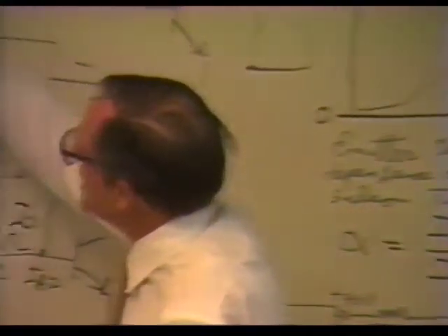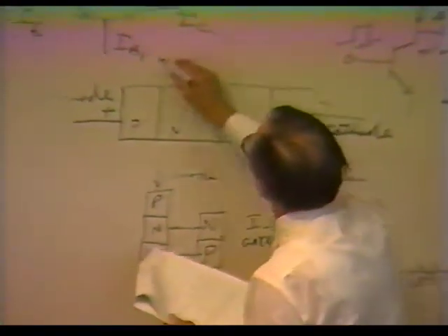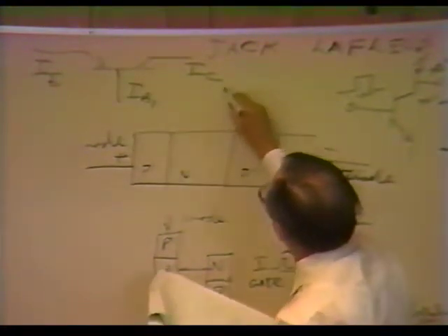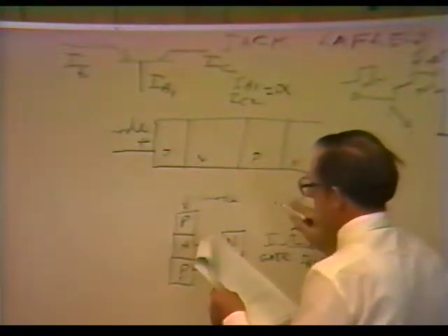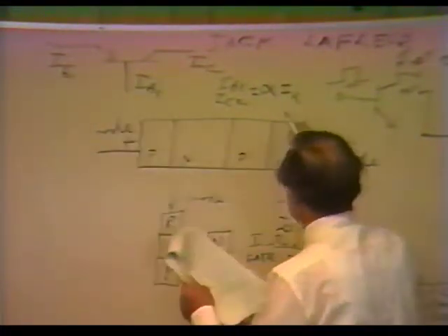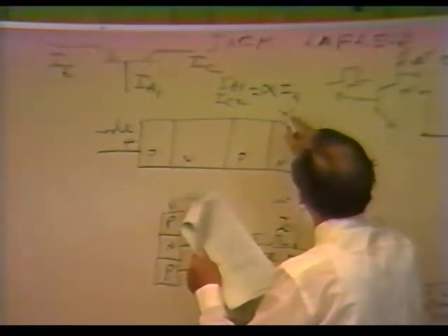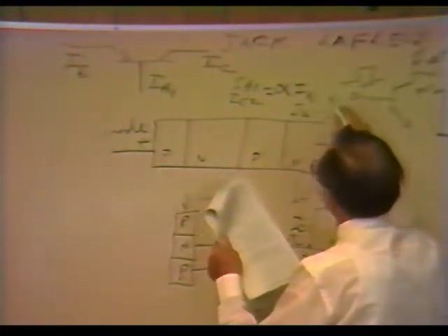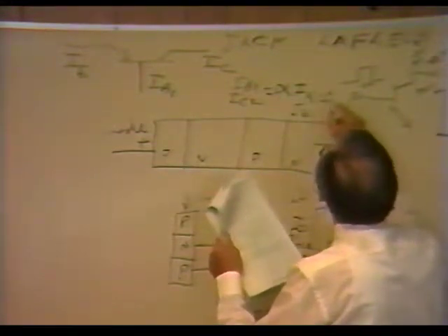So when we look at this transistor, and then it's the same as we have here, what we see is the base current coming out of here, IB1, is the same as IC2 that we said here. So it's the same current. IC2 and IB1 are the same currents. Now, they are equal to the alpha of the cathode current, IE, or IK, plus ICBO, which is leakage current, and for the moment we won't get into that.